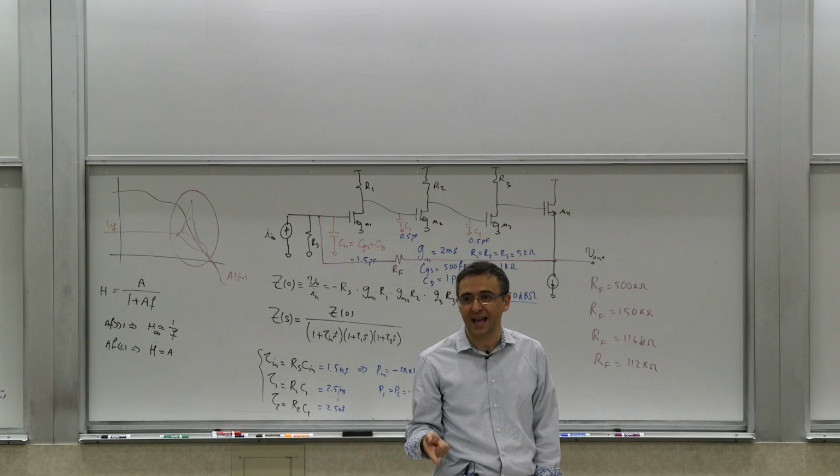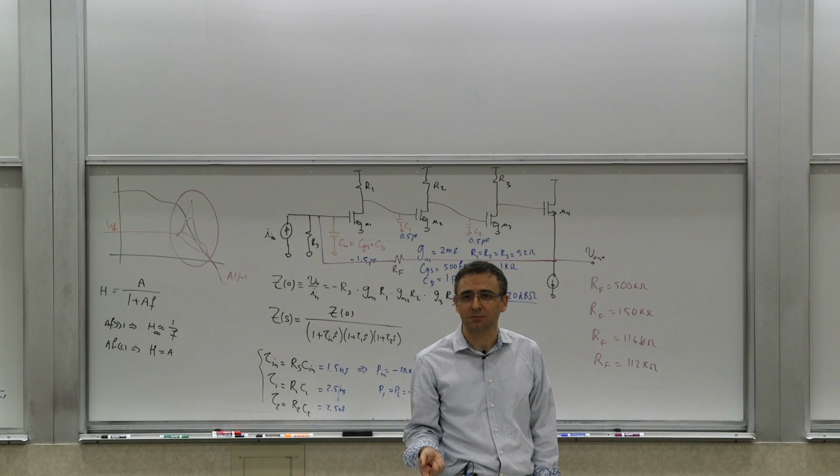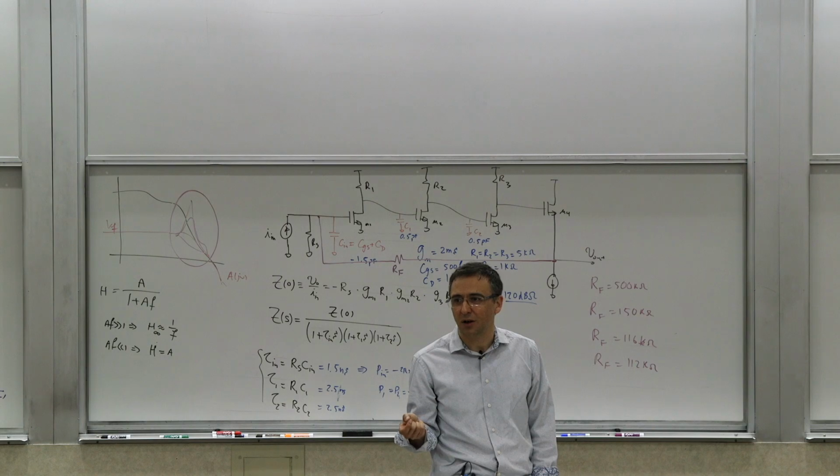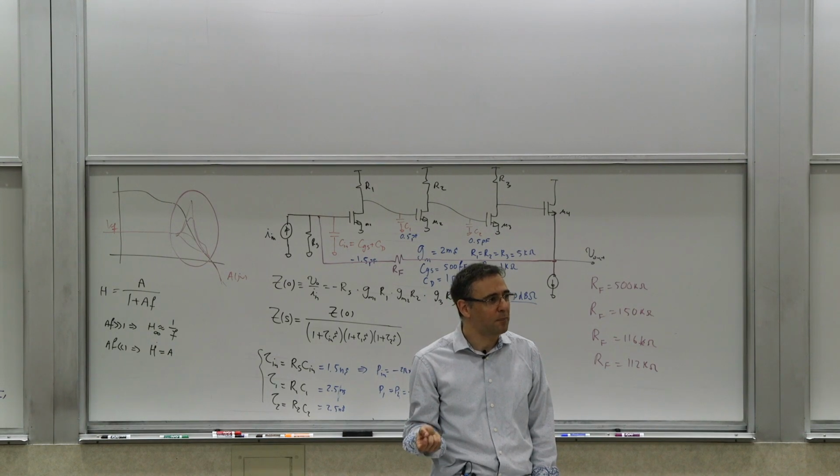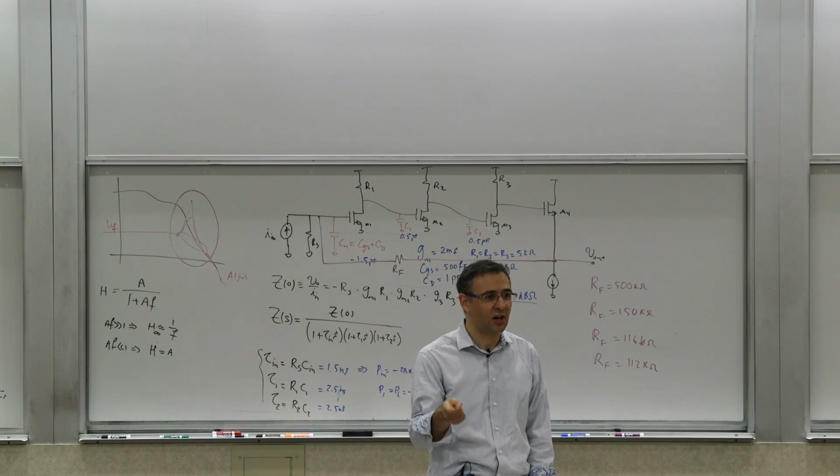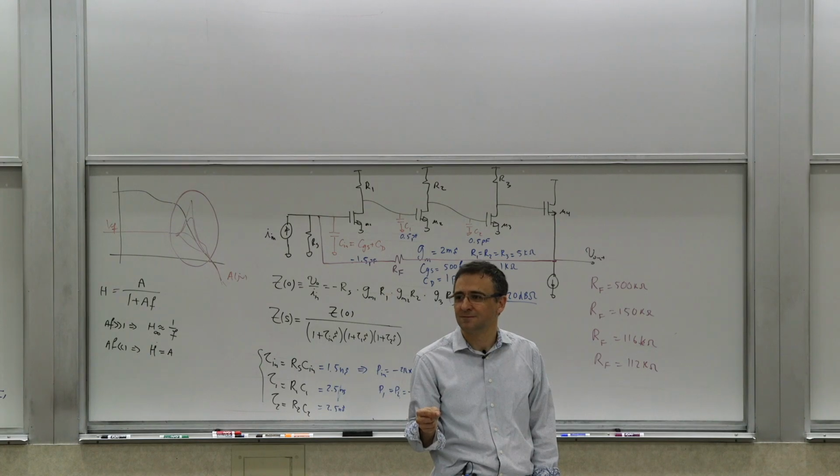If you look at just the frequency response, the linear Bode plot, and you were using that as a metric of your stability, it may appear that your system is more stable. So the lesson one is that you can't rely purely on the closed loop transfer function of the system and how much it peaks to say if something is stable or not.